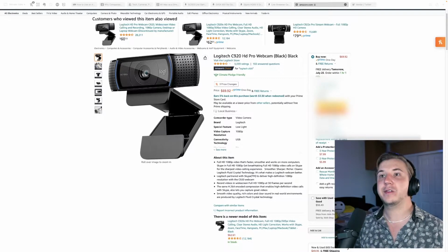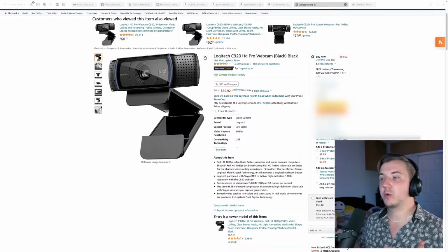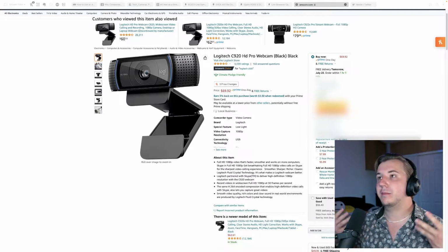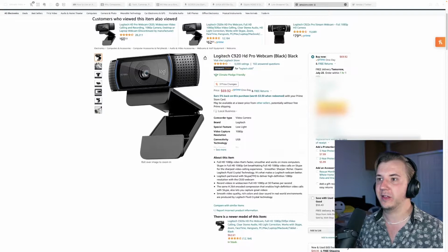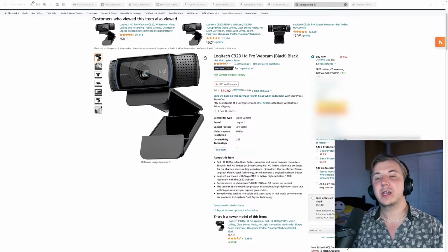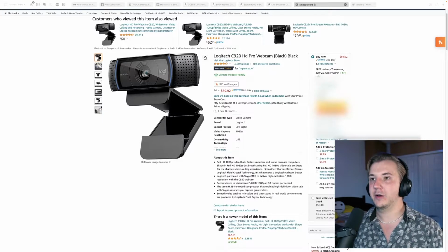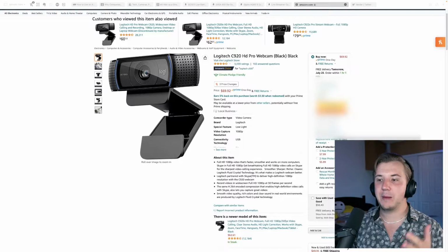But the point is, for both capture cards and for webcams or capture card plus camera combinations, it all needs to be UVC, USB Video Class Protocol, because UVC is driver free and it just works on MacBook. It works on Windows, Mac, and a lot of Linux without any setup, without any extra installation. But the gist is, if you're on an Apple Silicon device, you need UVC for your video. And that can range anywhere from your webcams to your capture cards.